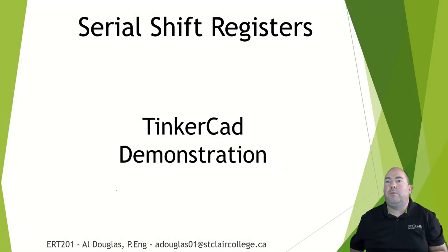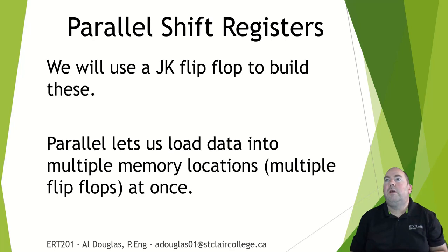Okay, we're going to move on from the TinkerCad demonstration. Now we're going to talk about the parallel shift register. Parallel uses a JK flip-flop instead of a D-type. Parallel lets us load data into multiple memory locations all at once. So we can load up a specific pattern and then run that because we can load individual flip-flops all at once.